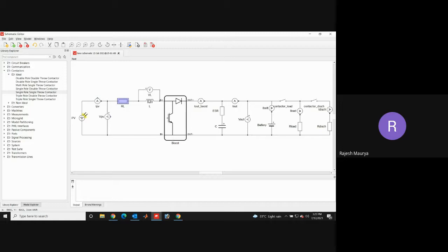Okay. And then for this inductor as L. So I have given the value for this resistor as RL and this inductor as L only. Whatever I have written outside it, I've just declared the same value inside it. Okay. Now here I do not require the signal output port for the signal processing part. So I'll not enable this one.